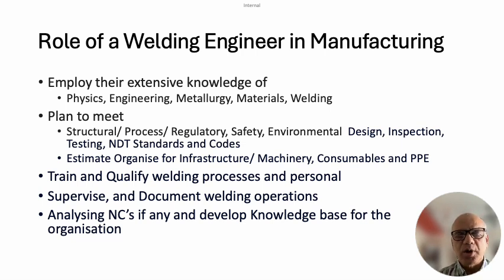One could be a rolled product, one could be a cast product, one could be a forged product, one could be a heavily machined product, one could be a heavily formed product, or both could be with all these complications and with different materials, different metallurgies. And to join them, we'll have to use another metallurgy or a combination of alloys by which we will be able to bring these two parts together and give them the required strength and soundness.